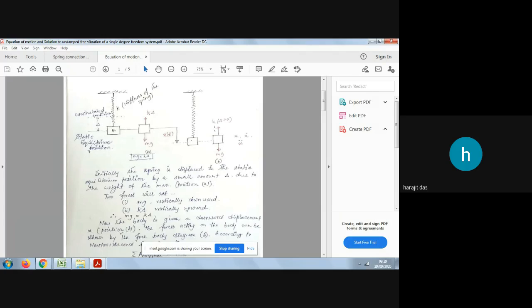Okay, on this system, this dynamic body, there is a spring force which is acting in the upward direction, so that system can be set to rest when you apply one inertia force which is exactly equal to mass into acceleration in the opposite direction.